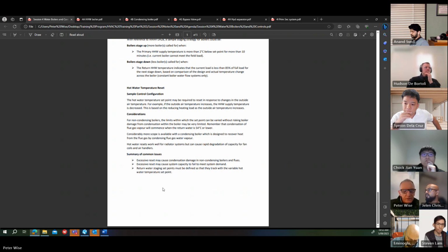I mean, yes and no authority, but I suppose a better question is, what's the flip side? If it wasn't sized to have enough pressure drop, what would then happen? Would you not be able to bypass enough water, or would you just not be able to control it well enough? You wouldn't be able to control it well enough if the pressure drop is too low.